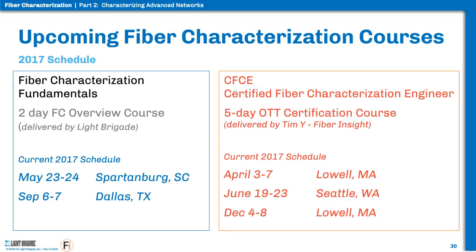And by using, for instance, in this case, the Viavi auto bidirectional, they've got a full bidirectional deal where they have everything in a couple of boxes, and you have a switch in there, and you've got automation scripts and everything else. And once I get that set up and ready to go, I can perform IL, ORL, OTDR, CD, and PMD in under 5 minutes each fiber. So I can actually perform that.